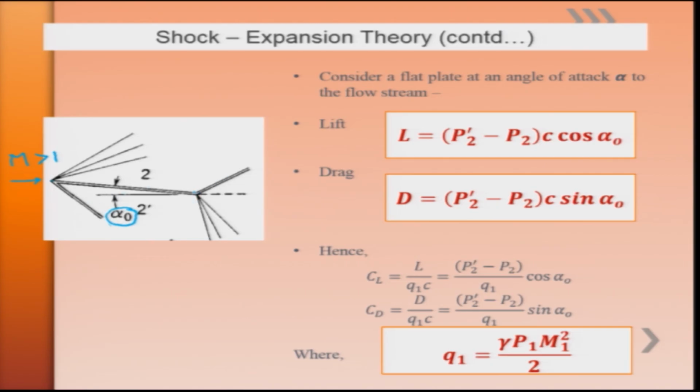At the trailing edge of the flat plate airfoil, since again the flow has to be parallel to the incoming stream, the flow has to turn into itself, and hence an oblique shock will be formed. Whereas the opposite case occurs at the lower surface, since the flow will be moving away from itself, and hence a centered expansion fan is formed.